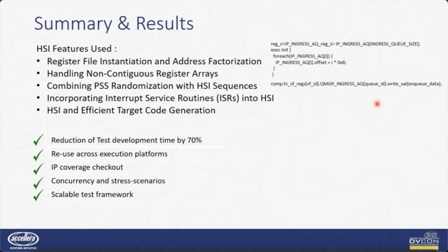You can still have your test bench, which is basically monitoring the interrupt signal, and whenever the interrupt is raised via DPI callbacks, you can call your ISR, which is written in the C code. And then on SoC level environment, where you have the embedded cores, you anyway program your interrupt controller as well, and then you have the standard way of servicing ISRs.